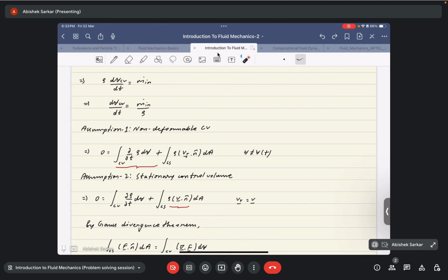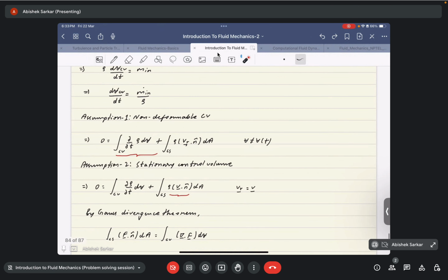So if the control volume is stationary, then the relative velocity would be equal to the velocity of the fluid itself, right? So once you put in these two assumptions, the non-deformable control volume, so the time derivative comes inside the volume integral, and a stationary control volume, so that V_R is equal to V, that is the velocity of the fluid.